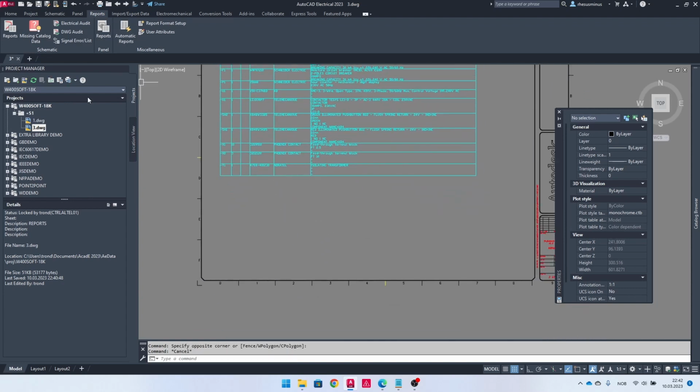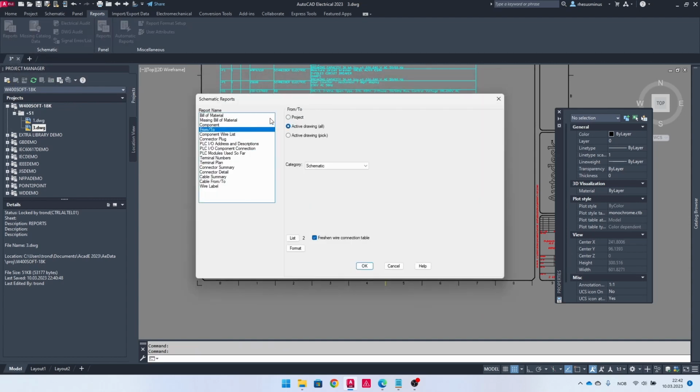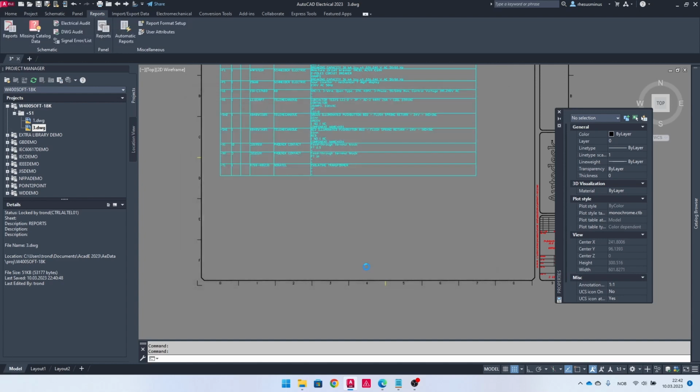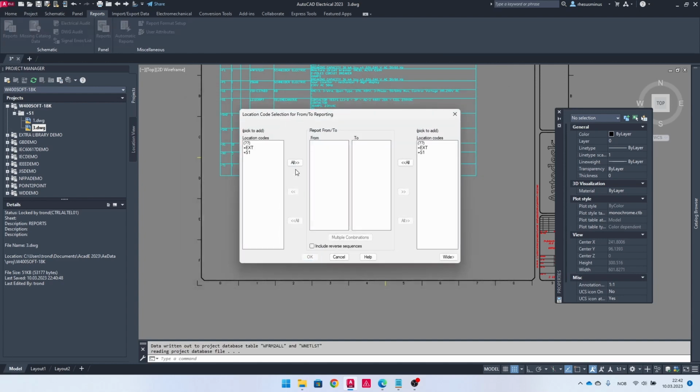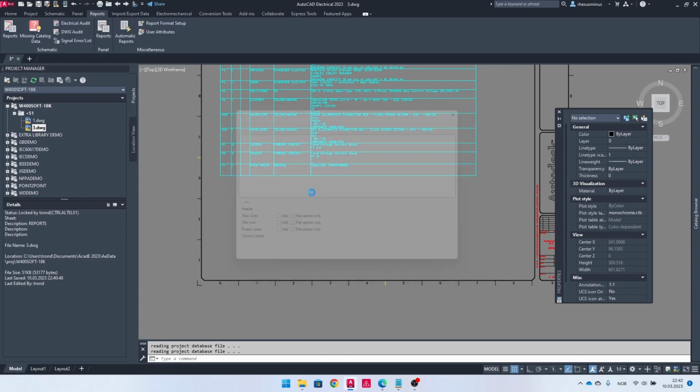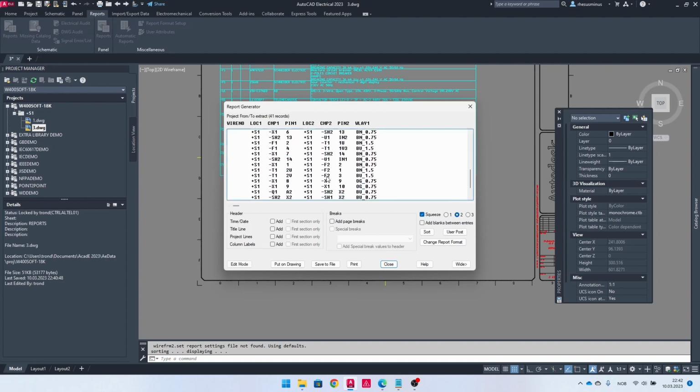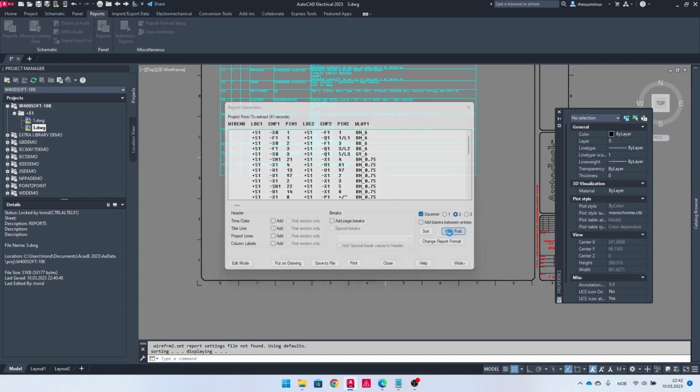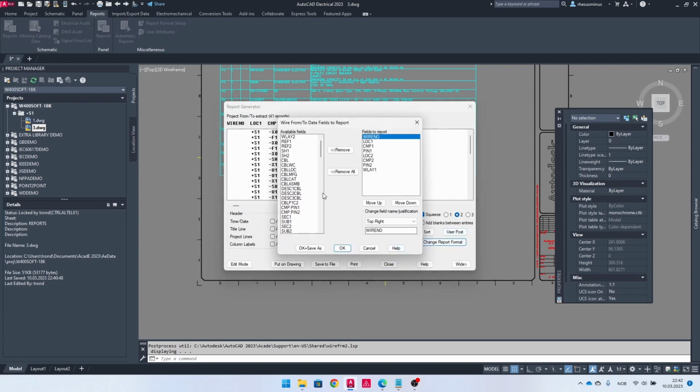And let's just see if we can get a wire list as well. So I will do the from to report for my wire project, and I want just things that are internal to the enclosure. I don't want anything that is connected to the external parts here. So I'll do OK for that one. I'll get a list here of all the connections with also the wire layer over here, what kind of connection it is.